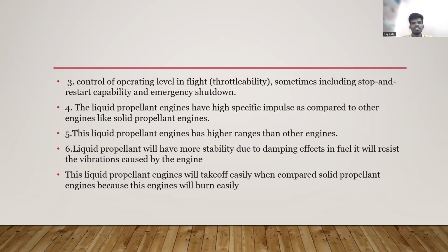Control of operating level in flight includes throttleability, and sometimes stop and restart capability and emergency shutdown. As we all know, solid rocket motors do not have any throttleability; they burn continuously and produce thrust continuously, and there is no chance of stopping them.